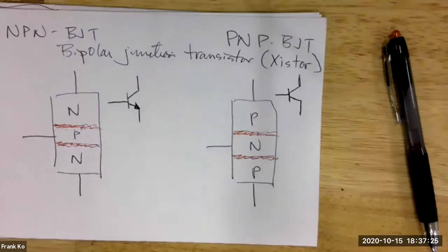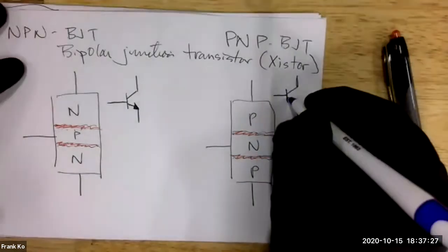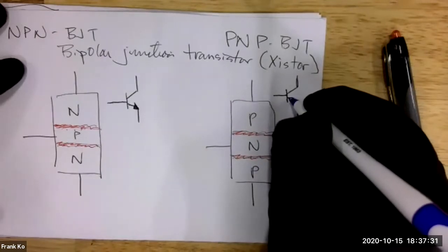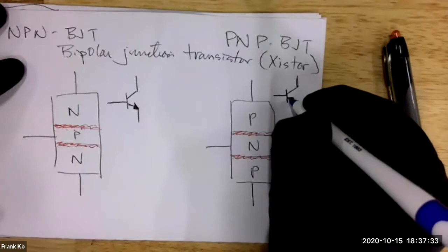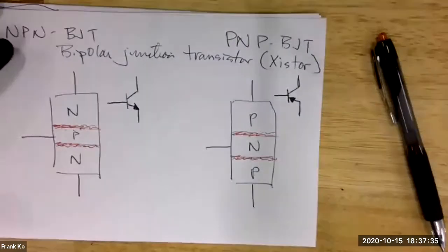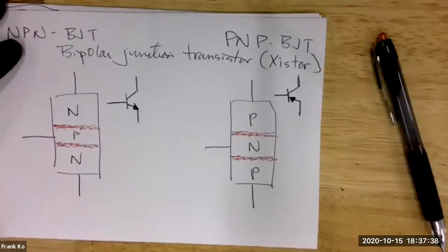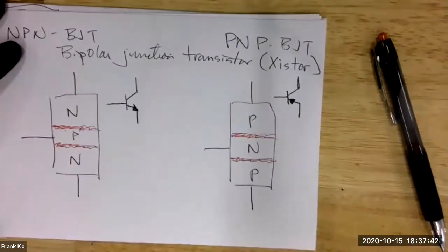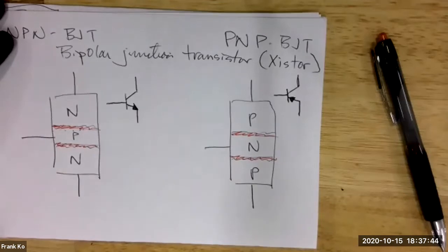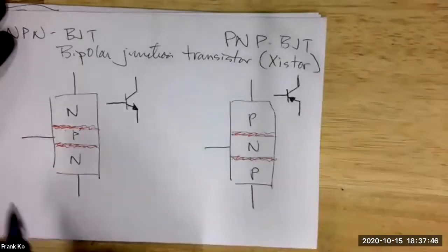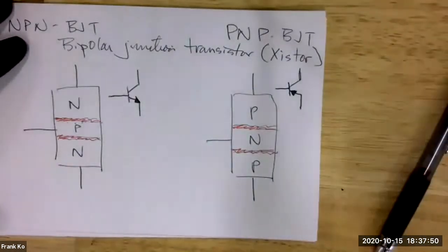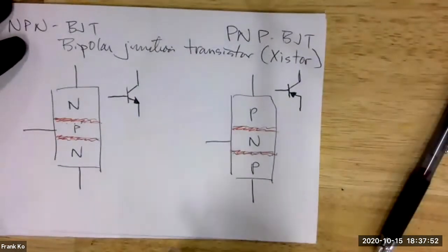On the other one, I'm going to draw a triangle right here. And the triangle here, in this case, is drawn on this, pointing into the transistor. So this one's pointing away from the transistor, this one's pointing into the transistor. And there's two things that I want to state for you that'll help you identify the leads of your transistor diagram.